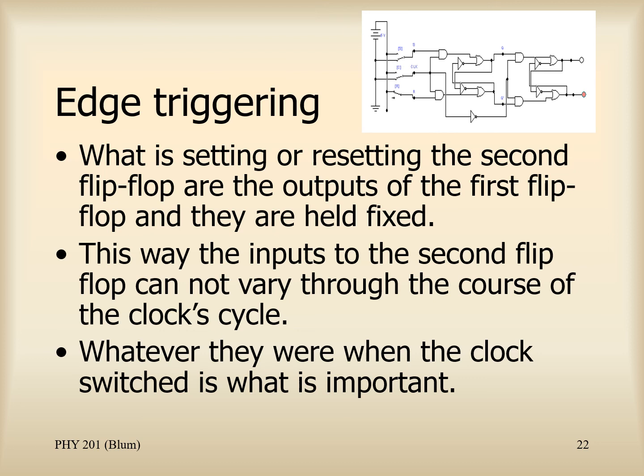So the inputs to the second flip-flop coming from the first flip-flop cannot change. They might change initially when the clock first changed, but they cannot change subsequently because what's controlling them is the first flip-flop, which is in its no change state. So only when the clock changes do we see any possible setting or resetting. This is edge triggering, in this case, negative edge triggering.